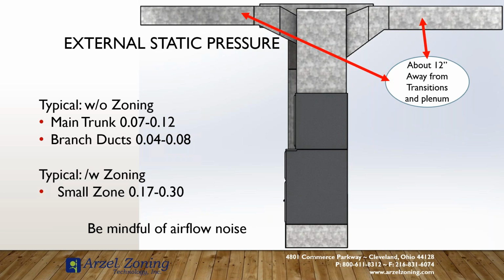So rather than looking at that friction of 0.1, we're now designing based on the velocity that we're trying to achieve. And the 0.1 is pretty close. And if we look at that 0.1 and we follow the line out, it gives us our CFM. We actually see that the other side of that static gives us our feet per minute. And when we follow that line out, we see that our feet per minute does end up within that parameter that we have for the Manual D chart based on the friction that we're looking to achieve.